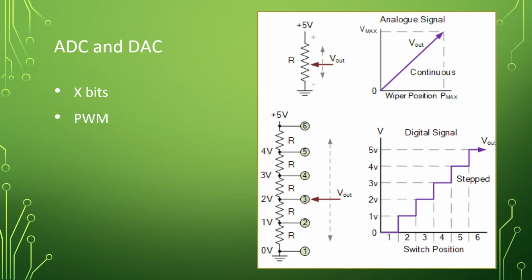All right. So let's say we're in the world of PLCs here, right? We're sending out 24 volts out of our output. And we got 24 volts here. If I were to turn my output on, and I took a voltmeter reading of that, it would be 24 volts, right? Now, what if I had it on and then off for equal amounts of time? And you took a voltmeter, what do you think you would read?